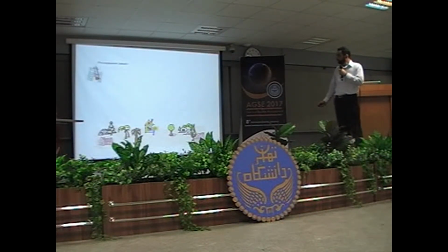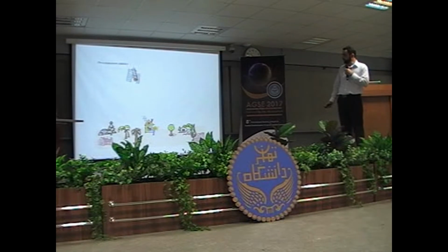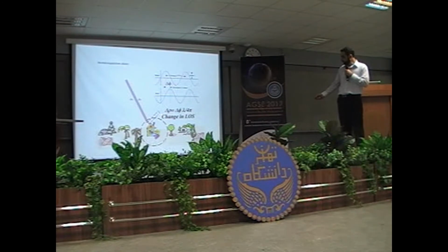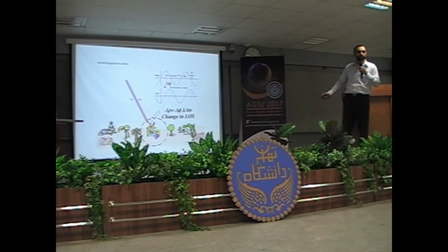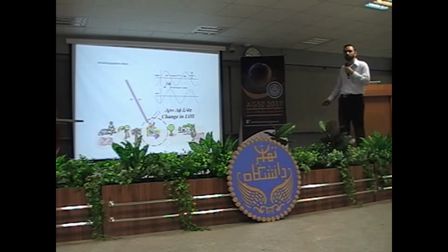This is the first acquisition that we call the master. The distance from the ground is calculated. And before the second acquisition, we have a subsidence. There's a subsidence here. So when the second acquisition comes, and again the phase is measured, the phase difference between these two images can give you an estimation of the amount of subsidence.